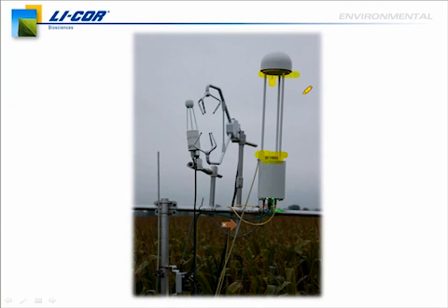As I mentioned earlier, we use that to measure temperature and make compensation as needed. This is a radiation shield on top of the instrument. This keeps us from condensing as much on the top mirror, and it allows us to run the heaters less. It's a power-saving technique that we found that will help us keep condensation-free optics without having to dump extra power into keeping the mirrors heated.